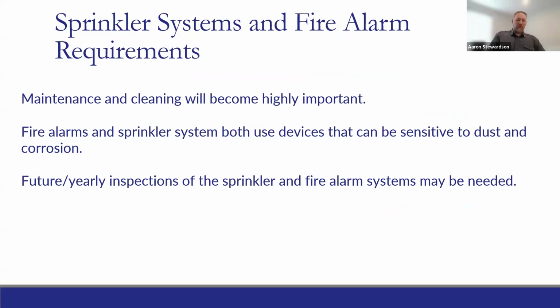Anytime we get into fire alarms with any building, it really comes down to maintenance, right? So one of the things that I have the scariest thought about here is that if a farm building is going to require a fire alarm system, you know, is maintaining those devices connected to it. Heat detectors, whether in ductwork or heat detectors in a building or carbon detectors, if they get full of dust, they stop working, right? So it really comes down to a lot of maintenance required for an owner to maintain those devices, and they may require inspections on a yearly basis.